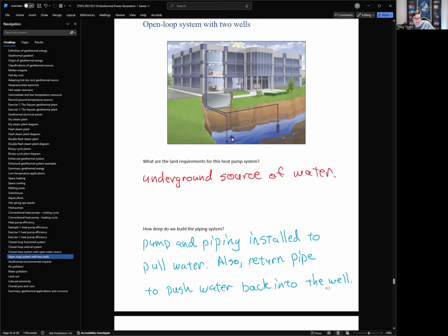If you put the inlet and outlet right next to each other, you're going to be pumping that warm water right back in. So you're going to have to space them apart so the warm water comes in and cools off before it goes back into the intake again. Okay. So if you notice, water is always a good medium for temperature control, right? We're just using it whenever we can. So those are your 4 different types of geothermal assisted heat pumps, and our conventional one we use for all of our houses.